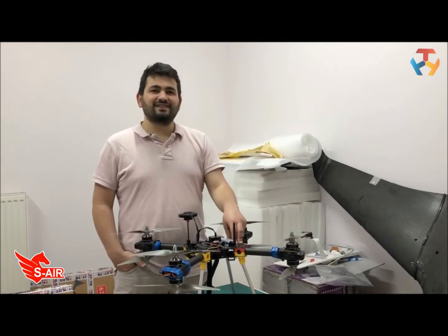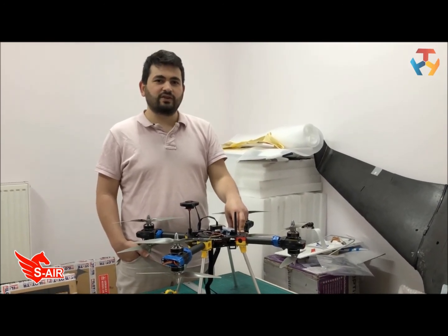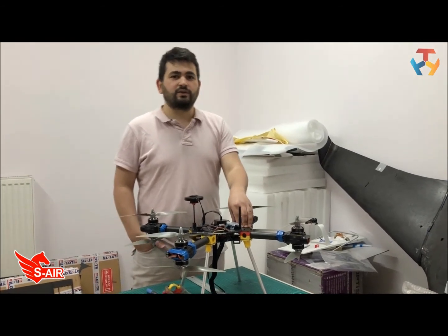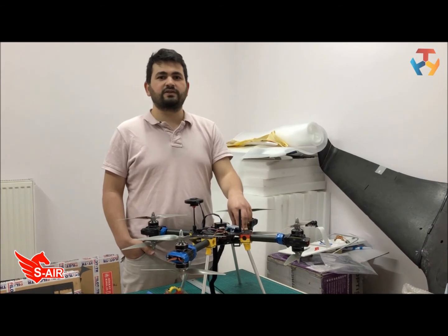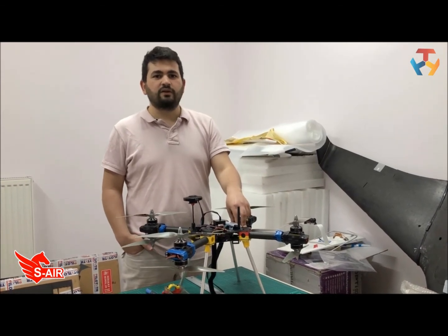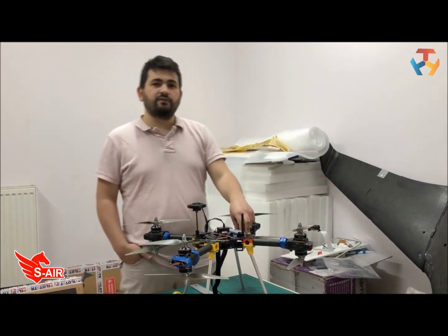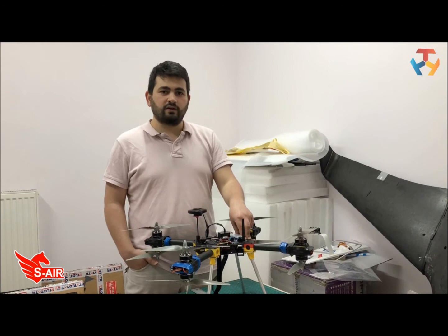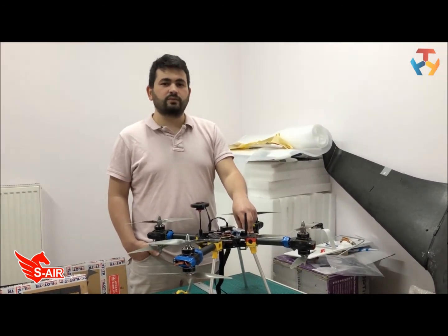We chose an X8 type airframe in order to provide enough thrust with minimum frame size and minimum weight. The propellers of the system are 11 inch and we designed a 580 mm size airframe for this propeller. Additionally, we chose 25 mm carbon fiber tubes for the arms for enough strength at maximum thrust of the motors.